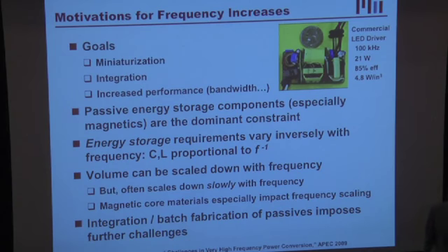However, in the real world, I should temper that a little bit. I talked about the energy storage requirements, and indeed the inductor and capacitor values, for example, do scale inversely with frequency. However, the physical component volume or size that I need actually scales down relatively slowly with frequency due to a bunch of practical constraints, some of which we'll discuss.